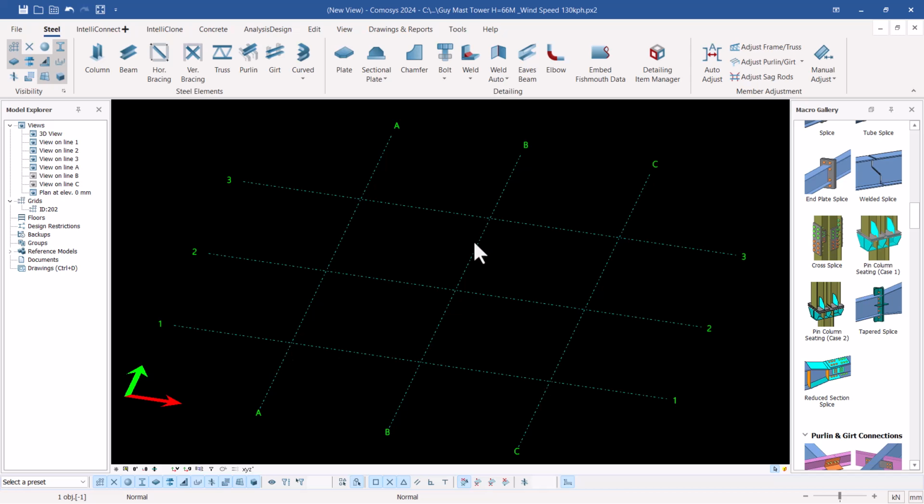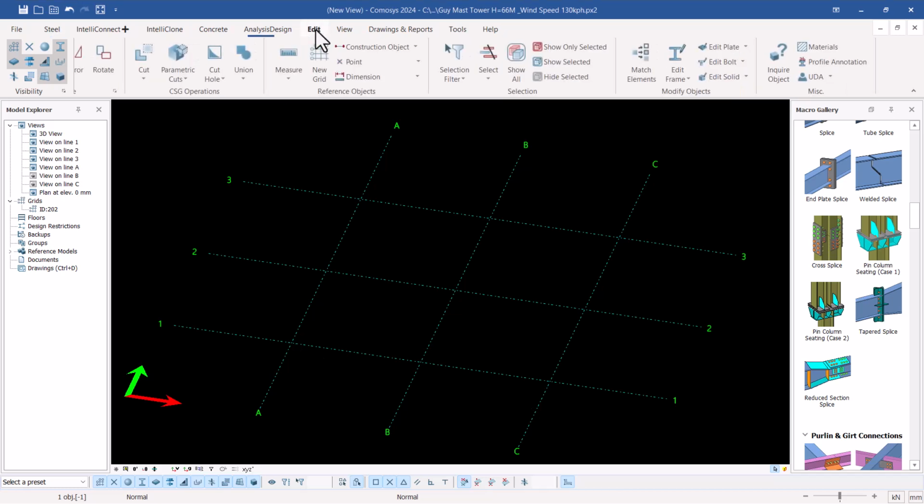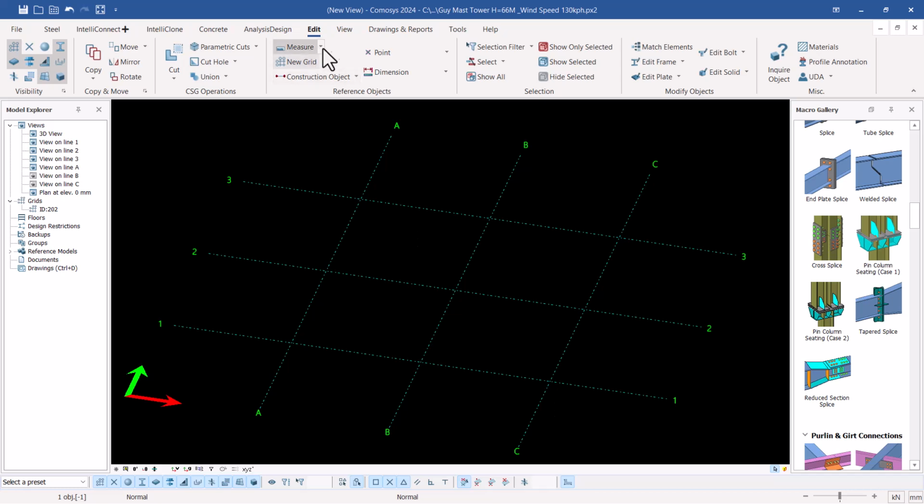Having this in place, we can place the first leg here and the first leg here, and now this one here will be a little bit tricky to place. I want to create the three legs here. Let me come here and click on edit, and measure this physically. If I come to measure and pick this part and that part, you can see it is actually 0.66. If I mouse over there, you can see 660 millimeter, and another leg should be somewhere here, but we don't want to approximate. So with the aid of creating an angle and intersecting the lines, we will locate that particular part.